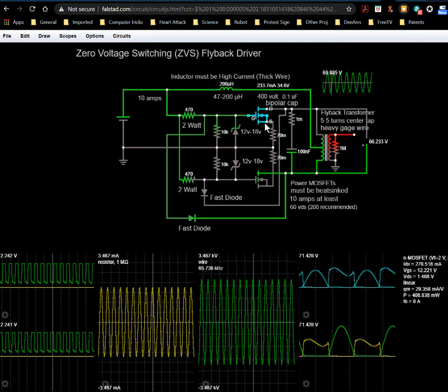Both drawing power at the same time is kind of a waste, because you don't want that. I think that's why these current waveforms look so funny. It might have something to do with that, I don't know. But the point is that when one turns on, the other one's not necessarily fully off yet, so there's a little bit of an overlap while the capacitance discharges. That affects the switching speed, how fast you can switch one of these transistors on or off.